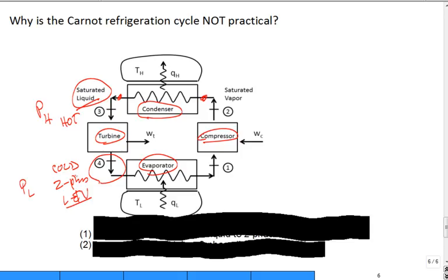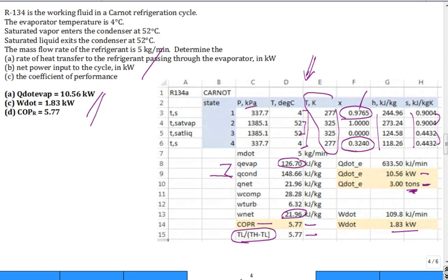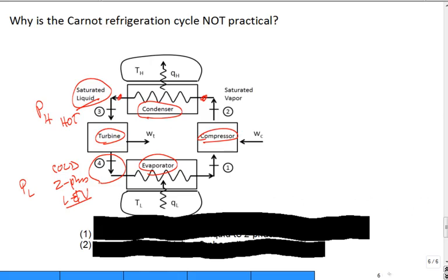So it drops the pressure. And you can even make the comparison: I put in a perfect turbine, if I could design and build one like this, and it wouldn't improve the performance that much. Test me on that. Check it out. Because how much work did you actually get out of that turbine for this example? Yeah, you got some out, but it wasn't enough to match what was going into the compressor. Okay, well, let's jump over here. There's one other thing. So this turbine is the big Achilles heel for sure. It doesn't exist, can't buy one, and you don't want to design and try to build it.